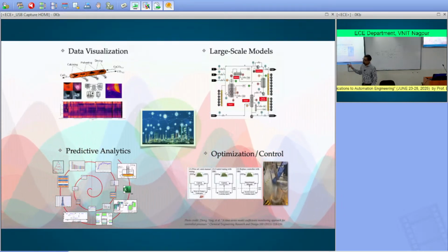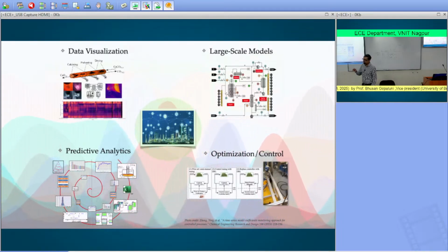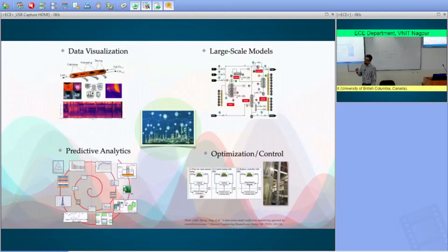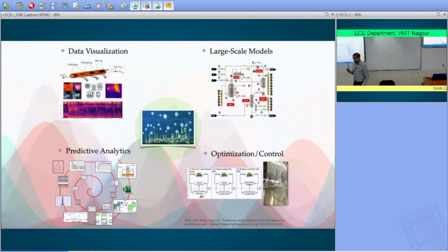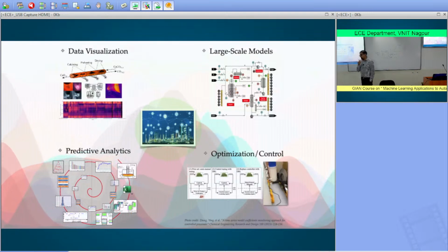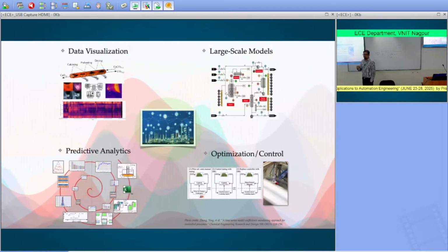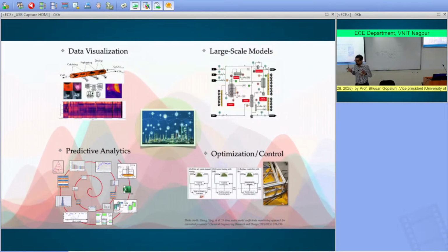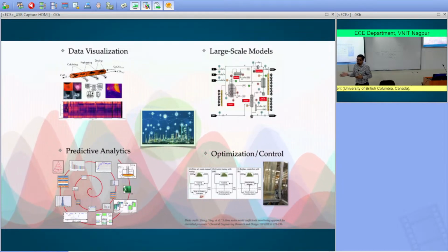Now, in this case, the controller was a PID controller. We designed a reinforcement learning agent on top of it, and the agent was adjusting the controller parameters: the proportional gain, integral time constant, and the derivative time constant. So it was tuning those parameters. The existing infrastructure, the PID loops, etc., they are exactly the same as what they had before. The only difference is you now have this controller or agent that's overseeing the performance of PID controllers.